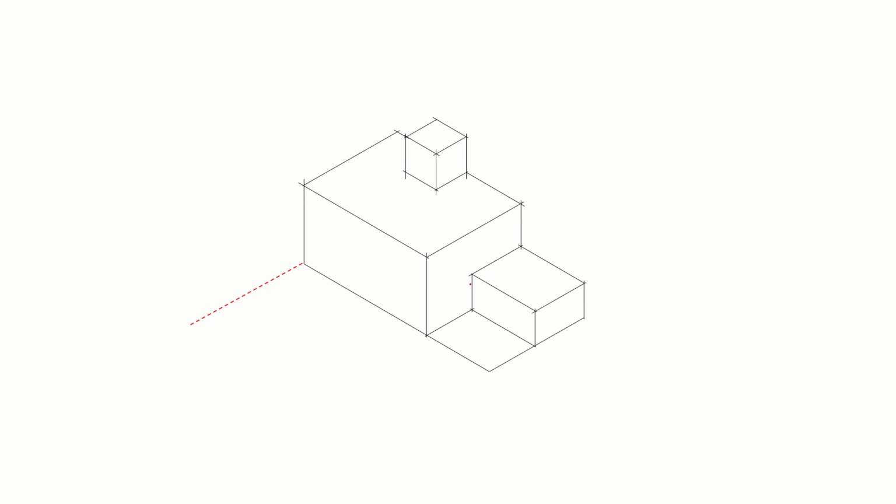How do we extract 2D from this 3D? We need to project all these edges back into 2D drawings, like I have done here. From here, I'm just trying to project. This line needs to be projected, this line, this edge, and this edge. Now I have got extended lines, so I connect these.